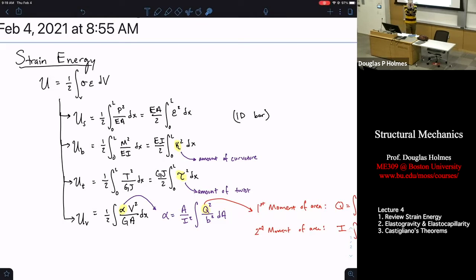Whereas if I bend it and cut here, it's still primarily a rectangular cross section. So bending is acting really just to stretch the top of this thing and compress the bottom, so it pairs with your elastic modulus. Applying a torque tends to distort the shape of your cross section, so it pairs with your shear modulus, which measures how much energy it takes to distort the shape. I point these out because I think these types of relationships are important for you to see immediately. The forces or moments you're applying should pair with the things that tend to resist those deformations.